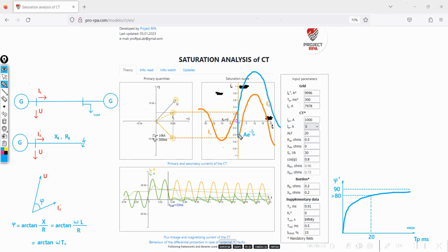As we know from the theory on alternating current, there is a connection between the phasor and the sinusoidal quantities. If we have a rotating phasor of one magnitude, then its projection on the imaginary axis gives the instantaneous value of the sine wave of that magnitude. If we take, for example, the phase of the short circuit current, which rotates counterclockwise from this position, then its sine curve will look something like this.